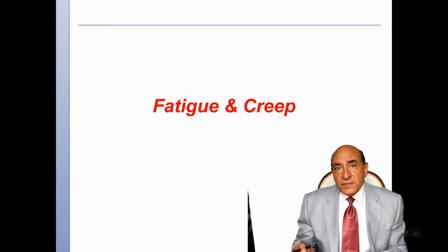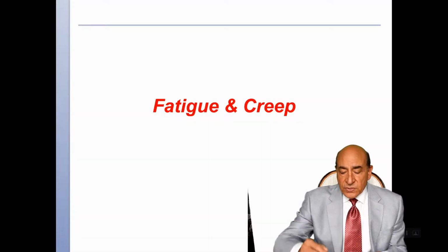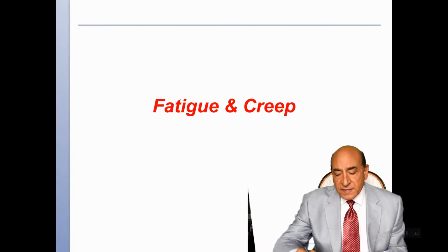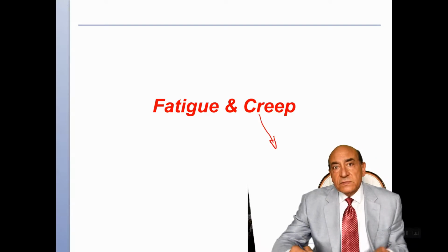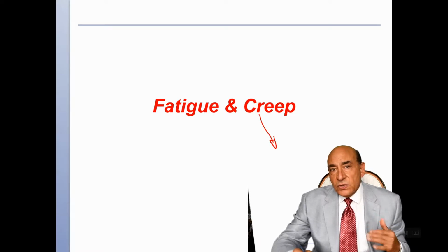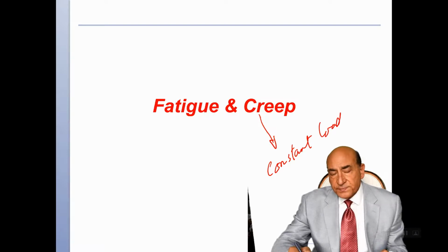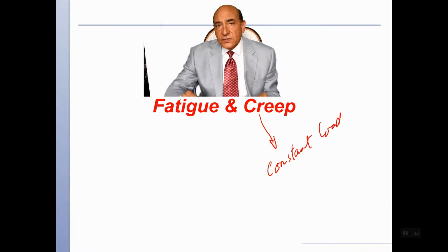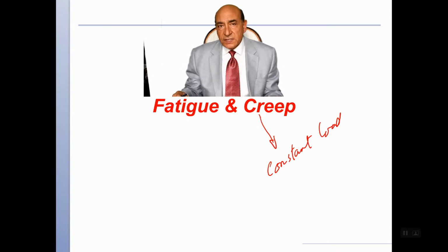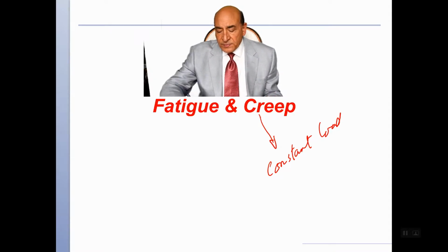For creep and fatigue, they relate to two different effects. One is continuous, where the load doesn't vary during the application. So this will be creep. So if we look at constant load, mostly, although in some cases the load can vary, but over a longer period of time. And usually this phenomenon is associated with long time behavior.